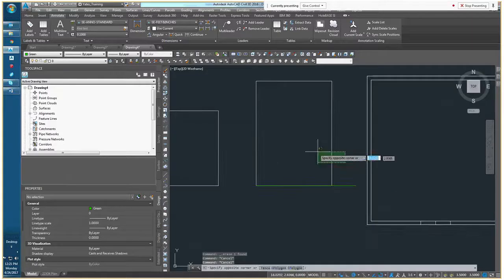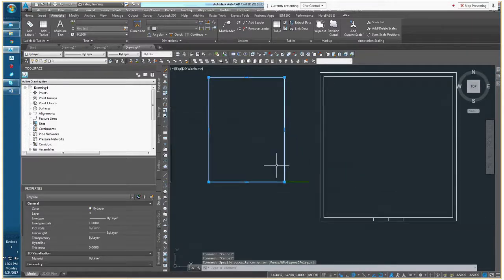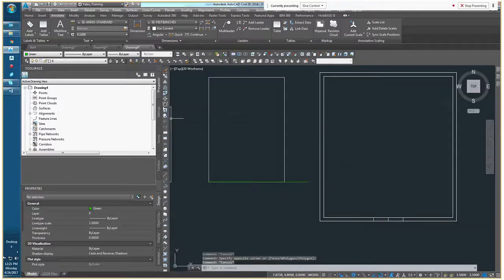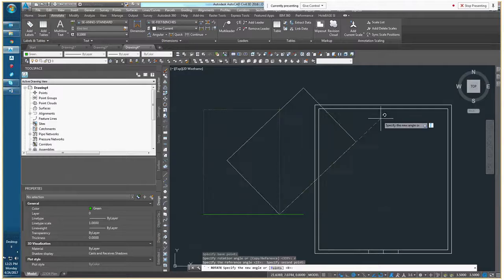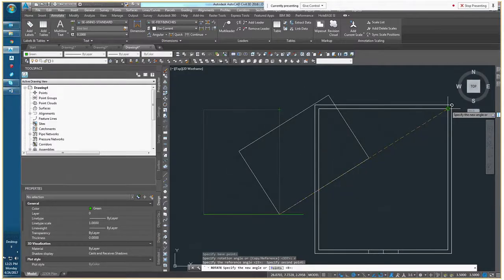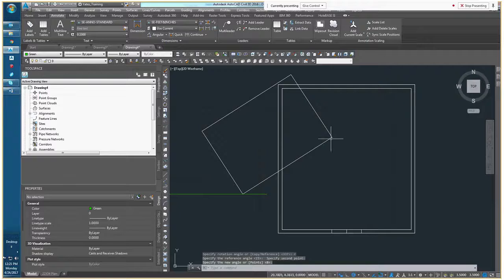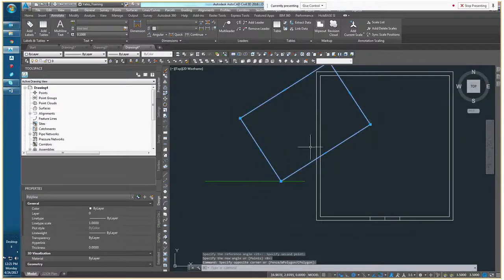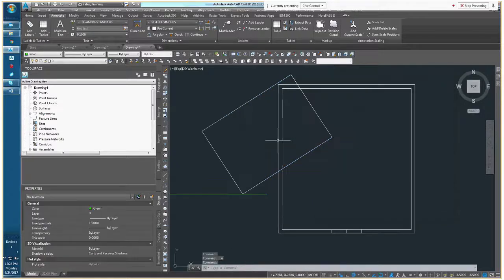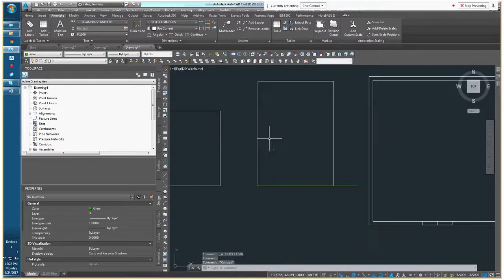But I wanted to show you guys that because it is extremely powerful. And it's so much quicker when you're trying to get objects rotated and set up based on stuff that's already there. 90% of the time, it is going to be based on stuff that's already there. Now, I'm just repeating this command, but here I wanted to reference something that's well off of its snap plane. It's way over here. I just wanted to rotate to that specific angle, so it's snapping to that outside box. And you see that's very easy to do. And it would be difficult to determine that angle on your own. So that is rotating based off of reference geometry.